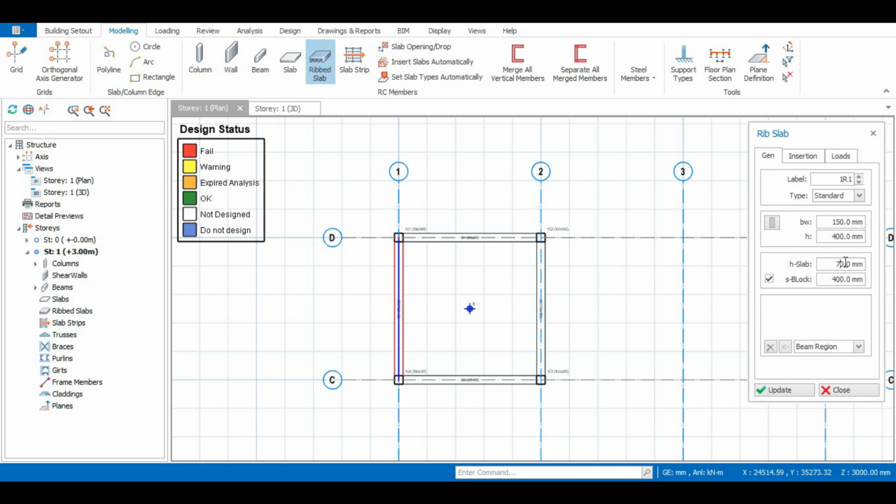And also, if you have experience added to your technical knowledge, you can use that to evaluate what you need exactly for your width here and then your height here. I'll be explaining this once we get into the design. And also, this is actually the depth of your main slab, which means that after you have your ribs, the height of the slab, what is left between the rib that composites the beam and then the layer of concrete that is above it. Let's just say the layer of concrete above it is this.